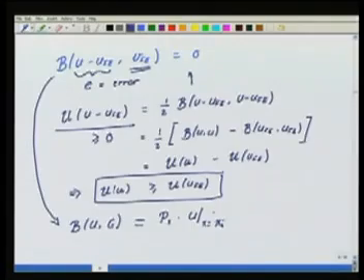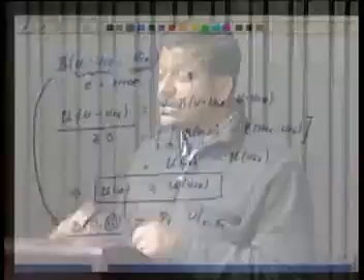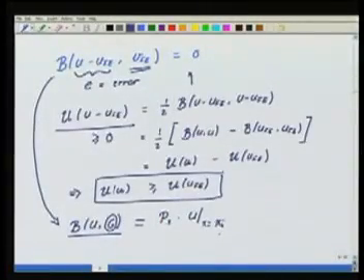This is nothing but the unit load method that you have done. What this says is that the strain energy, that is the work done by your existing state of stress against the strain due to this G, is equal to the work done by the applied force against the existing displacement. This is the unit load method that we have done in the mechanics class. This is going to be equal to u at the point x equals xi.